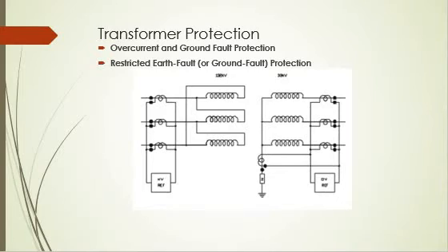When transformers are operated in parallel, it is not possible to adequately apply overcurrent protection for each transformer and also provide the necessary selectivity. The overcurrent protection for both transformers can operate for a fault on the LV bus of one of the transformers. It is usual practice to apply differential protection where transformers are operated in parallel. If overcurrent is used as backup protection on transformers operating in parallel, emergency overload conditions must be taken into account when determining the minimum pickup settings.